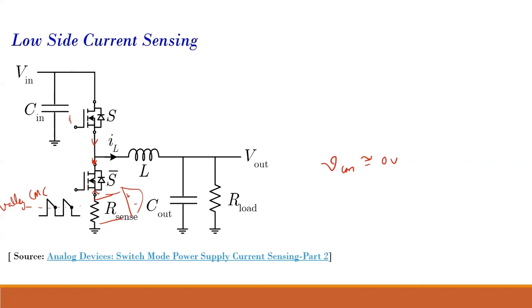Sir, this common mode voltage which you are talking about, does it decide the voltage that we can give to both the inverting and non-inverting terminals of the amplifier? Suppose VCM is equal to 4, then we can give a maximum of 4 volts to both the input terminals of the op amp. And also if one terminal is higher, suppose it is 4.5 and 4, then we can say the common mode voltage is 4 and the difference voltage is 0.5.